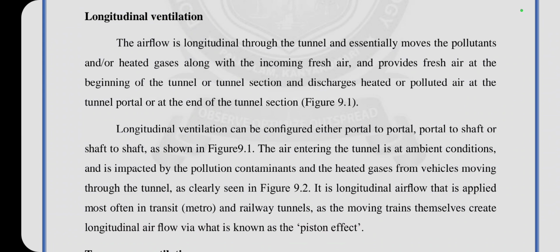The air entering the tunnel is at ambient conditions and is impacted by the pollutants, contaminants and heated gases from the vehicles moving through the tunnel. As clearly seen in the figure, it is a longitudinal airflow that is applied most often in transit and railway tunnels, as the moving trains themselves create longitudinal airflow via what is known as the piston effect.